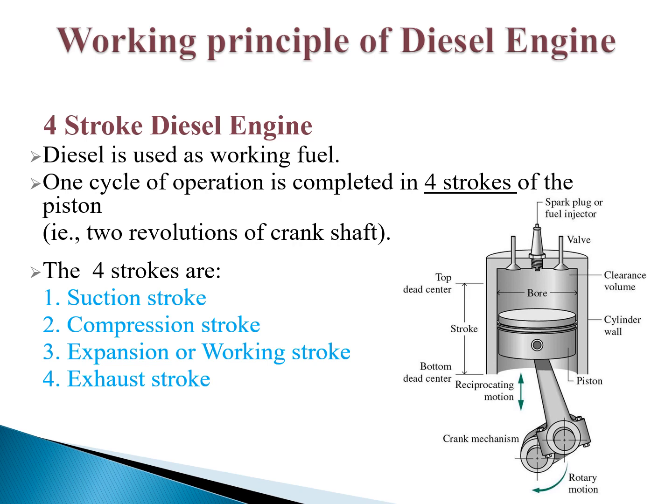Now let's look into the basic parts of an engine cylinder, given on the right corner of this slide. In this figure, we can see that the top dead center is the topmost portion of the cylinder and the bottom dead center is the bottommost position of the cylinder. The distance between the top dead center and bottom dead center is called the stroke.